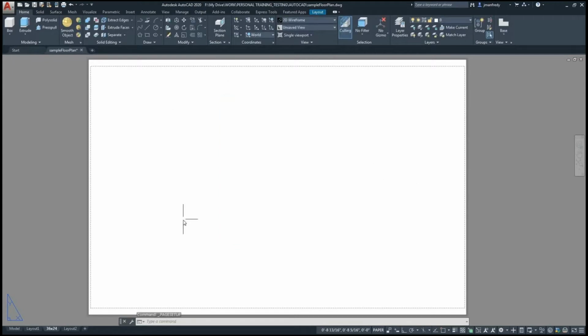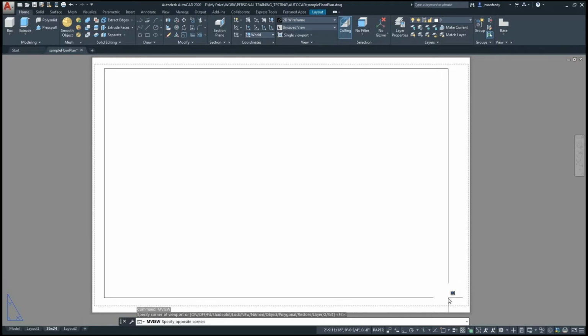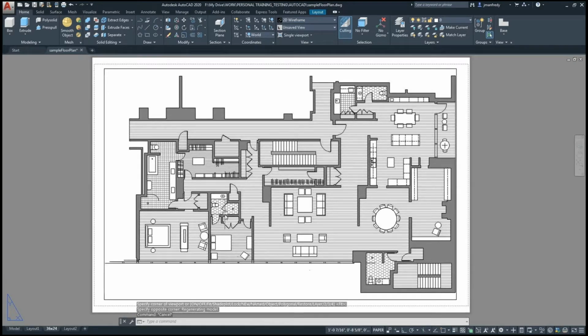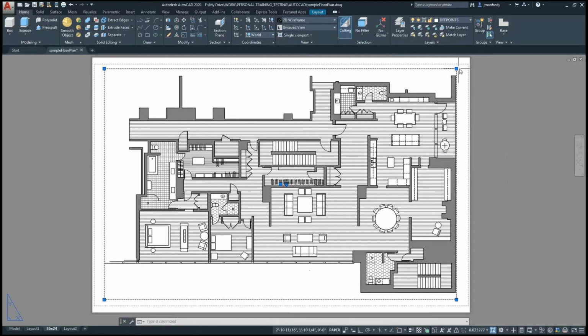Now I can't see my drawing from the model space because I haven't created an MVIEW, or the one that was here I deleted. So I'll make a new one, MVIEW, enter, and I simply draw a rectangle. And there's the drawing. I usually want to take this rectangle and stick it on the layer that does not print, like the layer that you make called depth points. Here, the non-printing layer. I'll move it over a little bit.